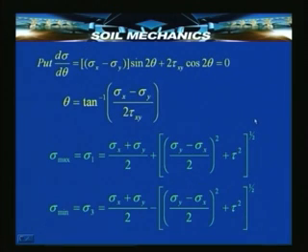In addition, as we have seen, there are 2 points D and B which have the minimum and the maximum stresses. How to compute these stresses? We can of course measure them off from the Mohr circle, which is plotted to scale, but we can also compute them. For computing these, we use this simple notion that sigma 3 is the minimum possible stress, sigma 1 is the maximum possible normal stress, and we already know what sigma is. We have an expression for sigma.